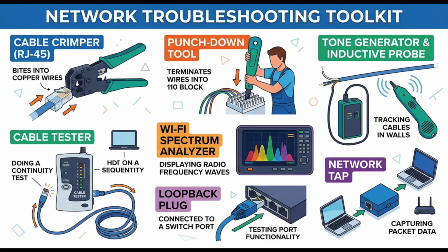And it does something else simultaneously, right? It isn't just about the electrical connection. Right. Secondary to the electrical connection, the crimper also pushes in a small plastic wedge near the base of the connector. It's called a cable stay. Okay, a cable stay. Yeah, and this wedge bites aggressively into the thick outer jacket of the main cable. It basically acts as strain relief. Oh, I see. That way, if someone trips over the cable under a desk, the pulling force is applied to the thick outer jacket, not the really fragile, tiny copper wires inside.